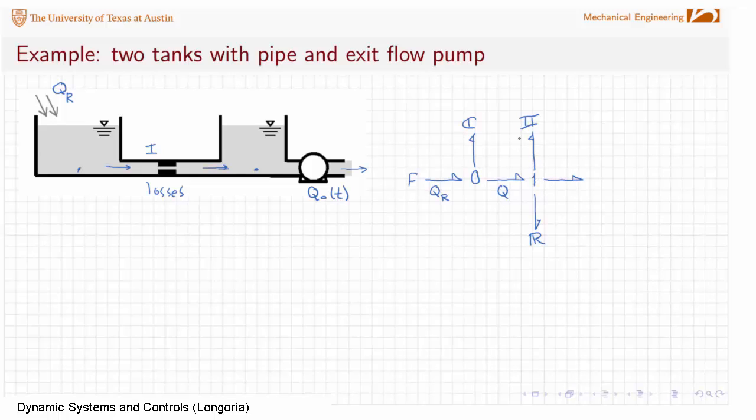But then there's some kinetic energy here that's being stored in this I element, and then it drops into another 0, right? Because we've got another tank and another C, and then finally we've got another flow source because I'm controlling this guy here.